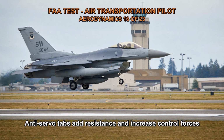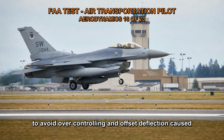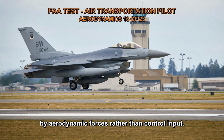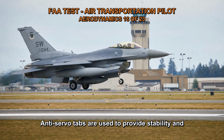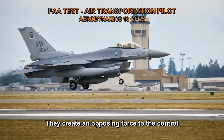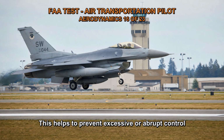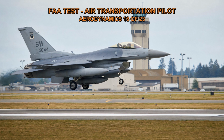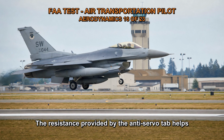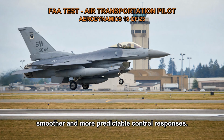Anti-servo tabs add resistance and increase control forces required as the surface moves toward its limit to avoid over-controlling and offset deflection caused by aerodynamic forces rather than control input. Anti-servo tabs are used to provide stability and prevent over-controlling of the aircraft. They create an opposing force to the control input, making it harder to move the control surface to its maximum deflection. This helps to prevent excessive or abrupt control inputs that could lead to instability or control surface damage. The resistance provided by the anti-servo tab helps maintain control authority within safe limits and ensures smoother and more predictable control responses.